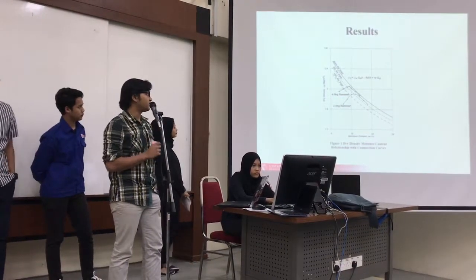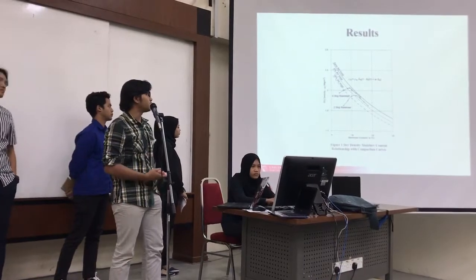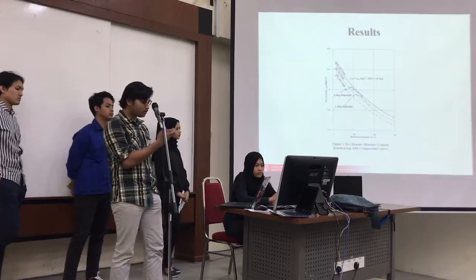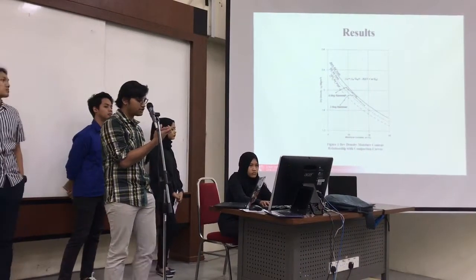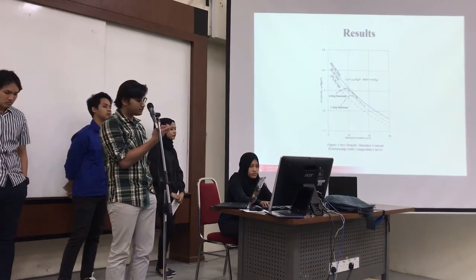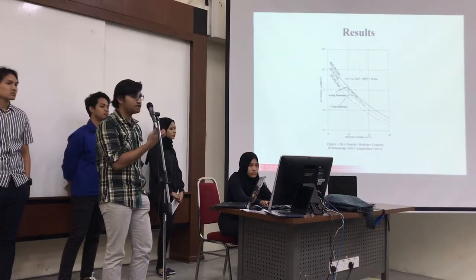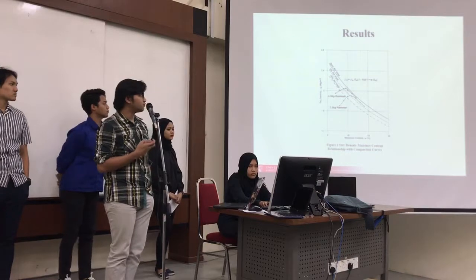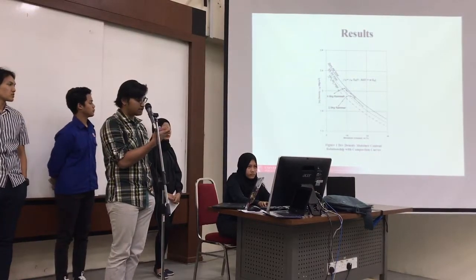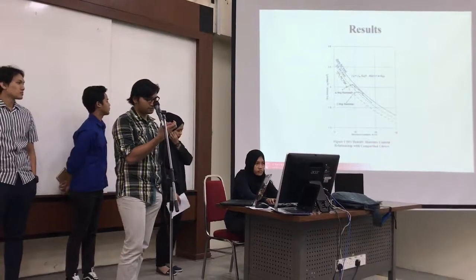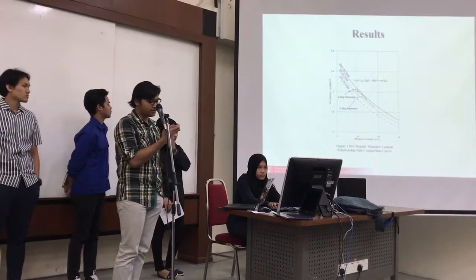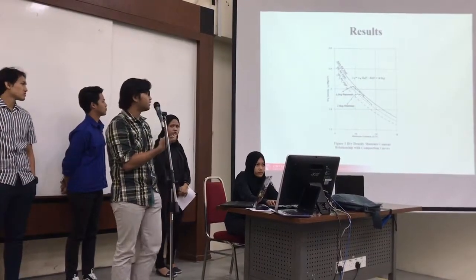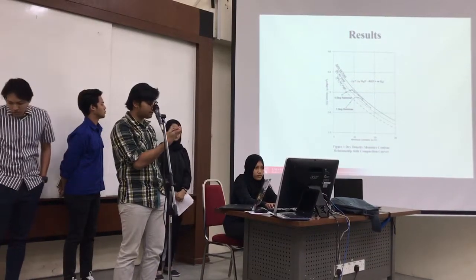What is meant by optimum moisture content is the water content at which the dry density is at its peak, at the maximum value. If excess water is present in the voids, the incompressible water acts as a retardant that absorbs and dissipates compaction energy, thus reducing the compactness. This explains why the dry density moisture curve in most soil types peaks at OMC, optimum water content, and curves down on both sides of the peak.